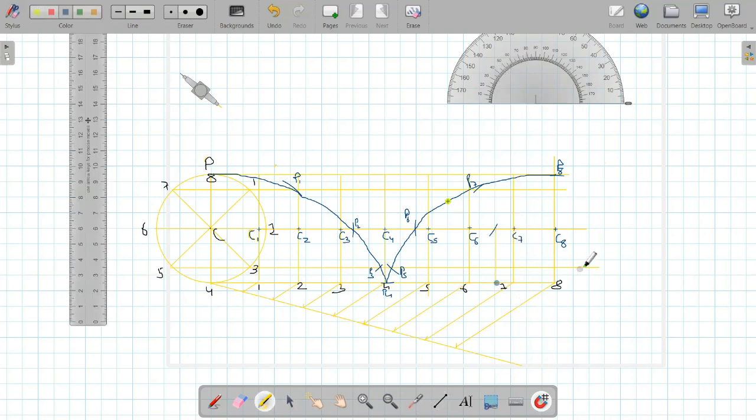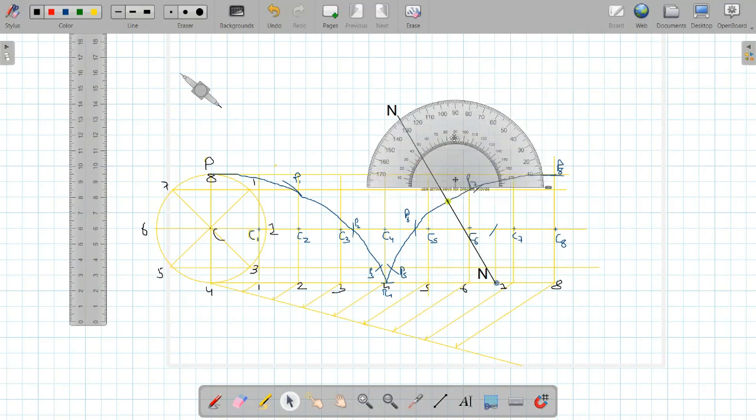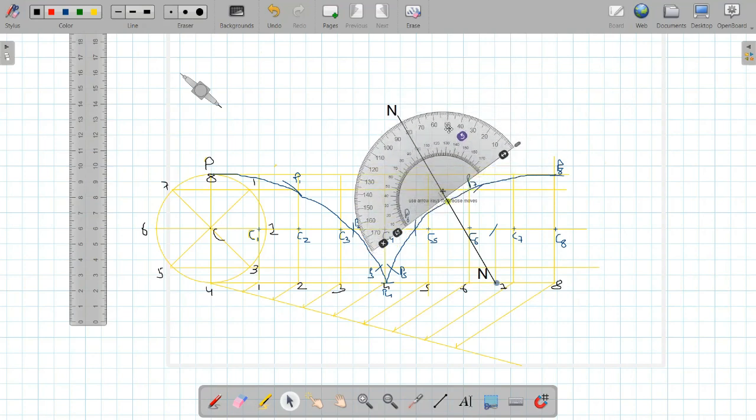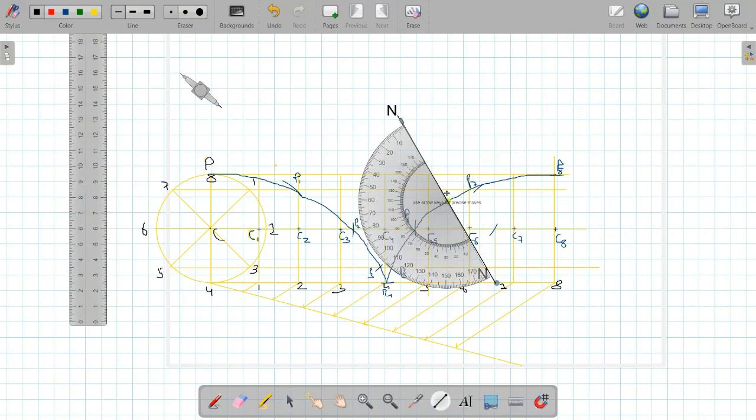Then wherever this arc cuts on the center line, we have to draw one vertical line connecting the circumference line. Now this point where it cuts the circumference line has to be joined with the point on which we want to draw the normal and tangent. Like this. So this line which we have just now joined is nothing but the normal. And now we know that normal and tangent are always perpendicular to each other. So we'll just take our protractor, mark 90 degrees here.